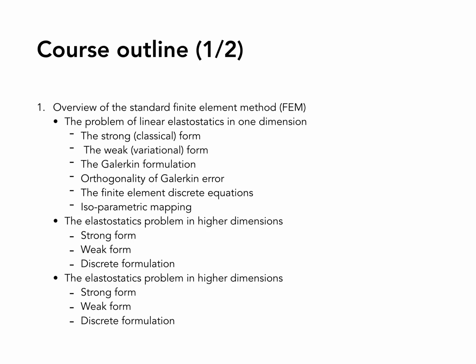So we will look at the classical problem of elastostatics in 1 dimension. We will start from the strong form, which is your equilibrium equation. Then we will get from the equilibrium equation the weak formulation, right? Or what some people refer to as the principle of virtual work, or your variational formulation, it has different names, which is basically an integral version of equilibrium.